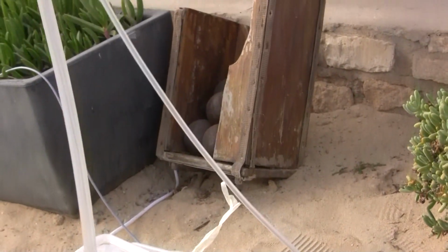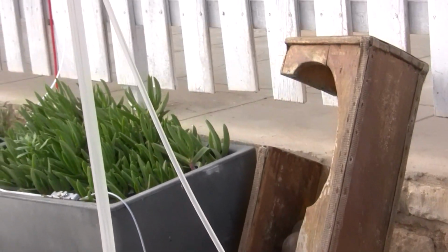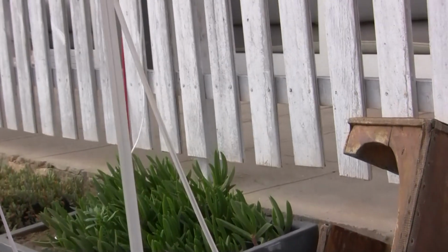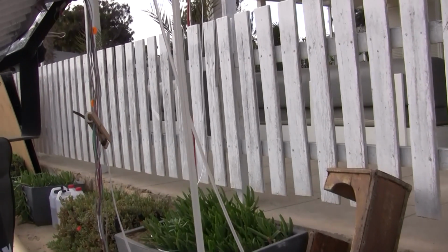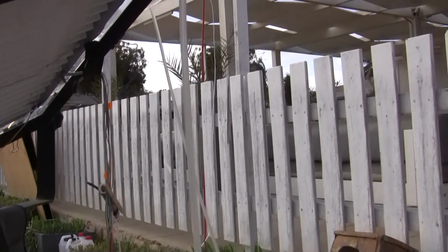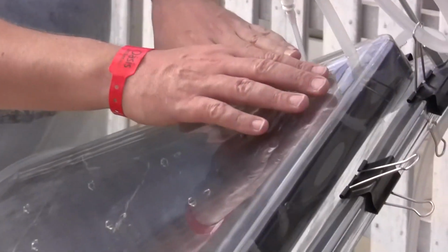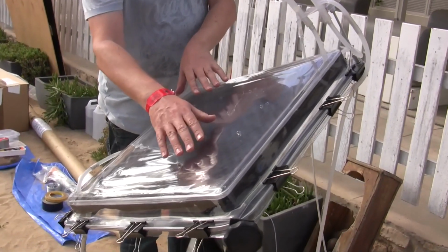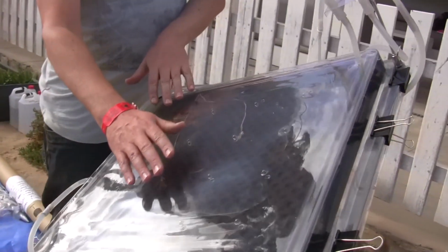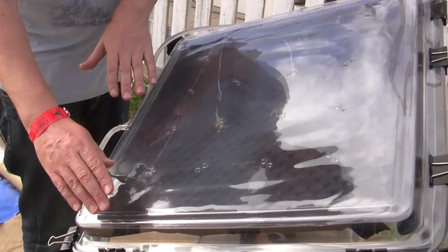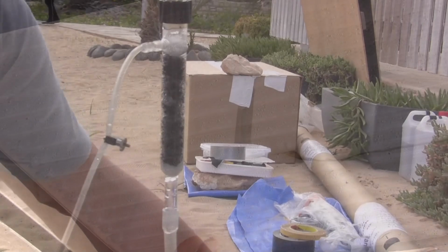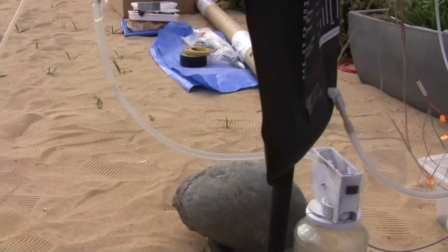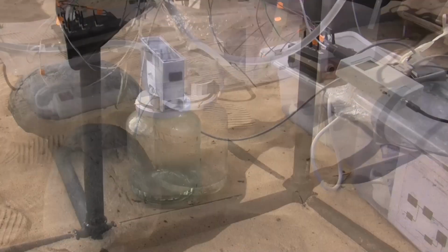During operation, the water-containing glycerol solution, or hydrated glycerol, enters the multi-layer structure of the water extraction module, which is heated by solar radiation. The water molecules of the heated hydrated glycerol evaporate, and the water vapor passes through the water vapor permeable membrane. After passing the membrane, the water vapor condenses on a surface that is cooled by the ambient air. This pure water is then collected into a storage vessel. Our final product? Drinkable water.